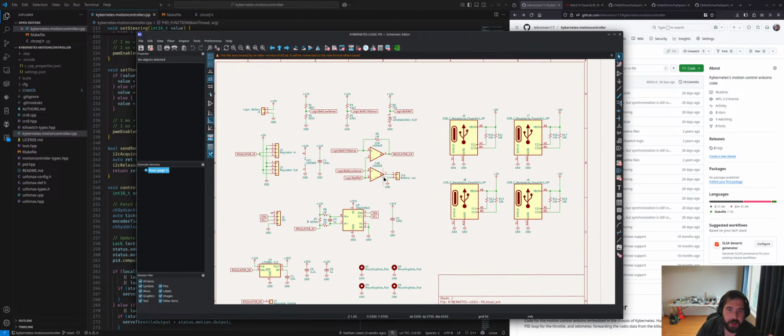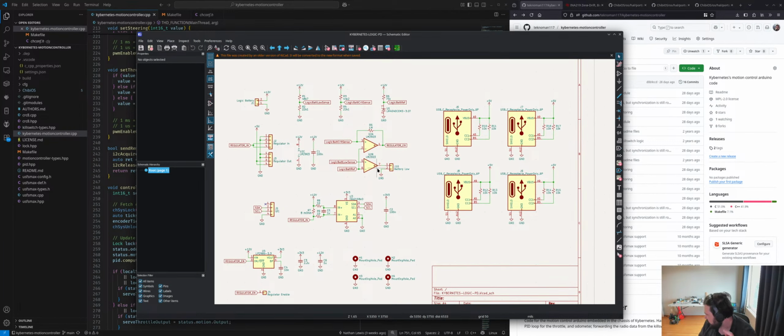Either way, the robot has an I2C connection to this board, and that I2C bus connects to this current sensor. It connects to an IMU, which we may get to today, but we'll probably do in a future video. It also connects to the onboard what I call the kill controller, which, unless the trigger's being pulled on the radio, turns off power to the motor controller, so that there's an out-of-loop dead man switch.